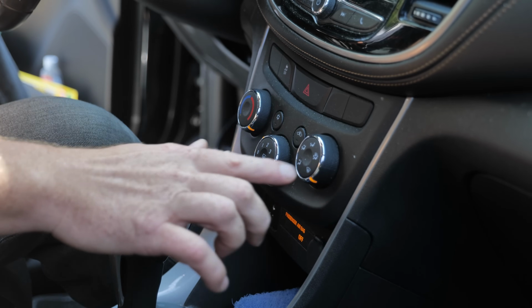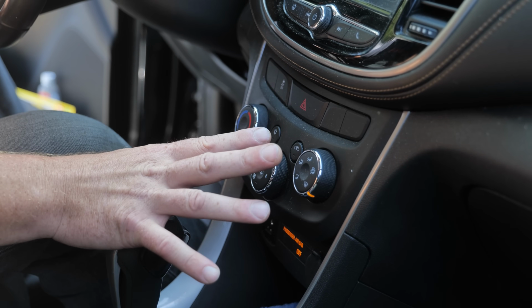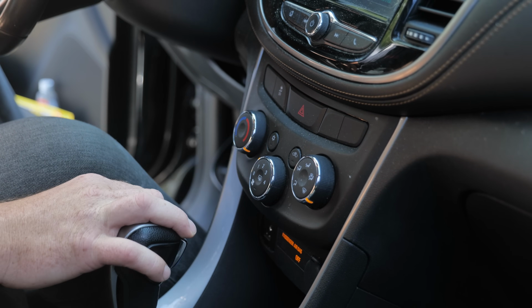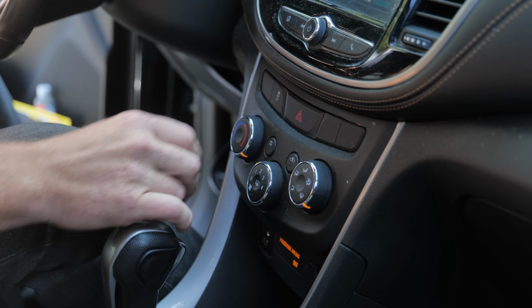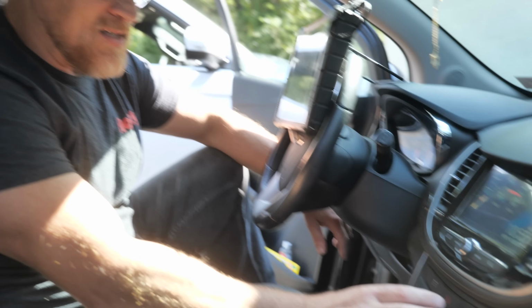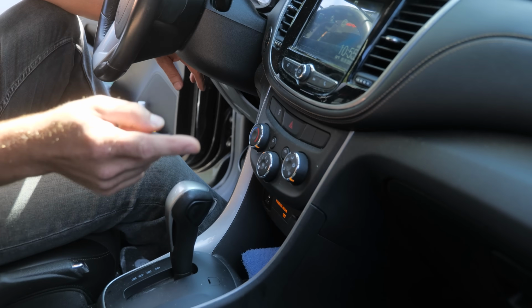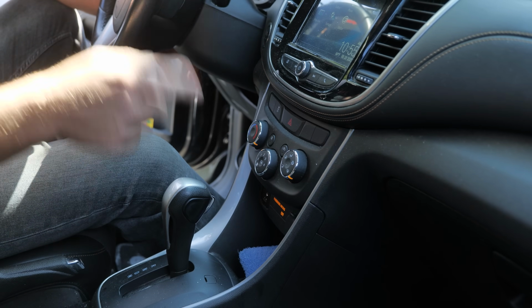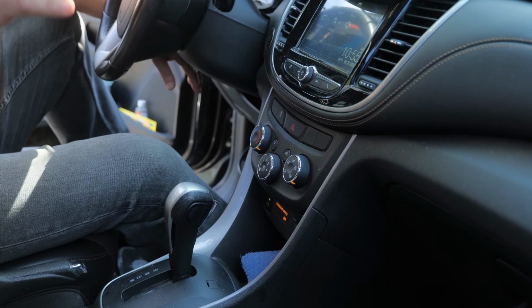Chevy Trax. There are two versions from when I looked at the service info before we got here. Two versions of HVAC controls. There's a manual and an auto. There is no auto button. There's no temperature display that I'm seeing. So this is suggesting to me that this is just a manual system. The automatic AC system used a pulse width modulated blower motor. The manual system has resistors, but on both of them, the resistor assembly, if you want to call it, is an electronic device too. There's a module inside of it.